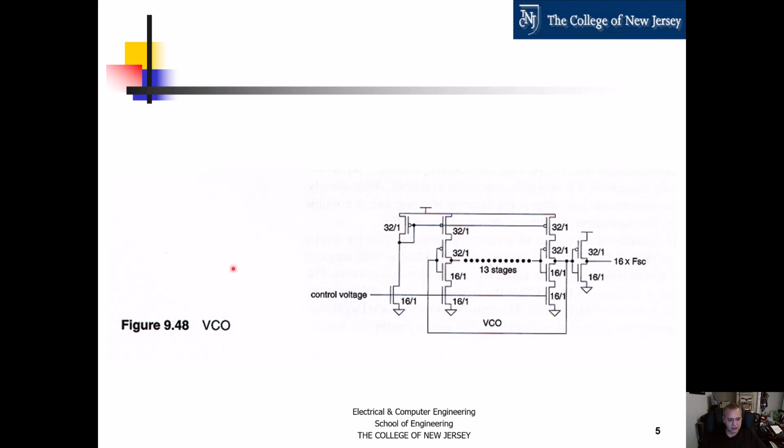So you will get some type of transfer curve that is going to be sort of like an S, not perfectly linear. There's going to be like a tilted S, but in the middle there will be a very reasonable linear operating region of control of frequency output versus control voltage. And that's how the oscillator works. And when you put it all together, then it works. You have the whole PLL that works as I described at the beginning in the first slide.